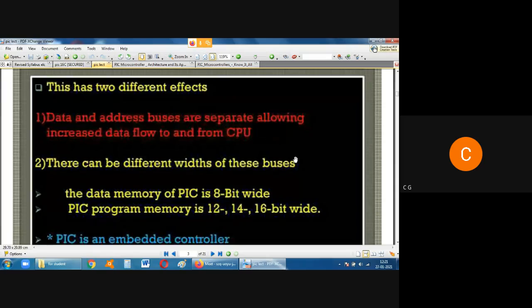I have given you the idea: instead of adding the two numbers using the adder-subtractor, why can't you use an op amp as an adder or subtractor, the circuit that you have used in MSc? If you divert the addition to the op amp, there is no need of a clock pulse. You give the numbers, and immediately you get the answer. But with full adder and half adder, you need a clock pulse.